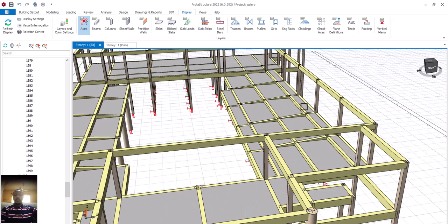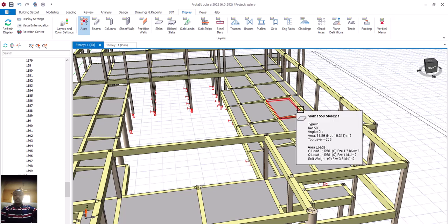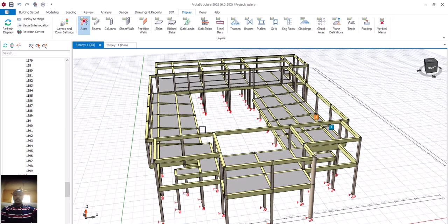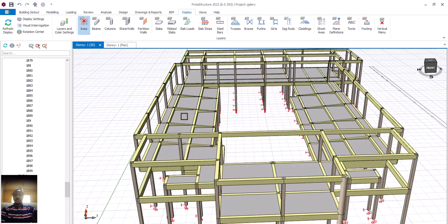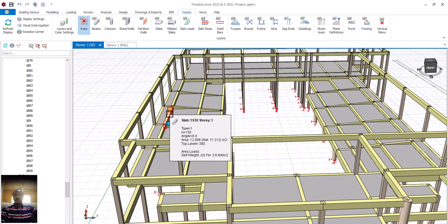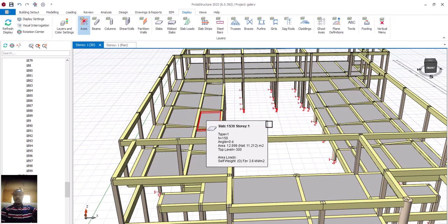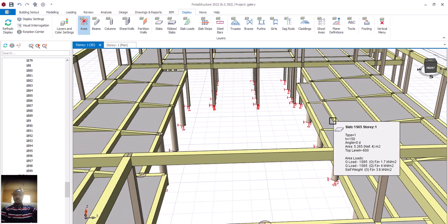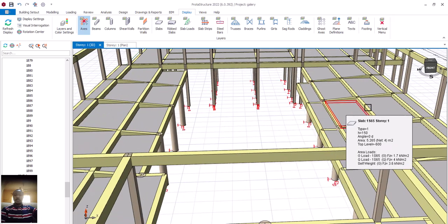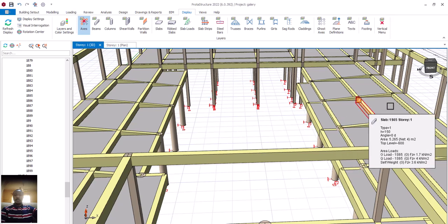And in this place I will use 225. Is that okay? Another architect might come and say 300. The architect might tell you from here to this place 300, that you step down by 300, and that one step down by 300. And we have seen some galleries in the form of a staircase, very easy, from here to this place 150, from here 150.